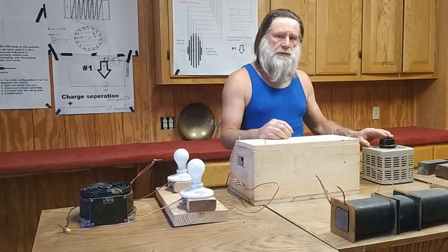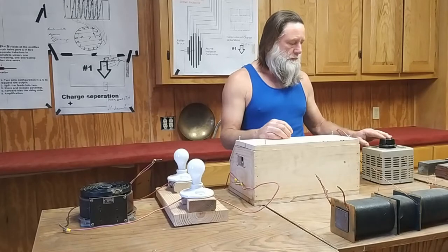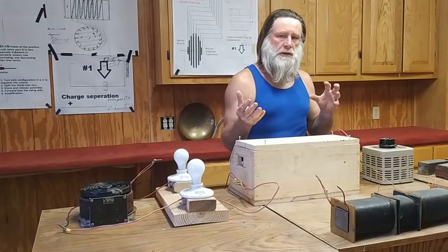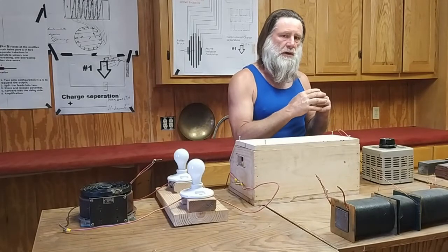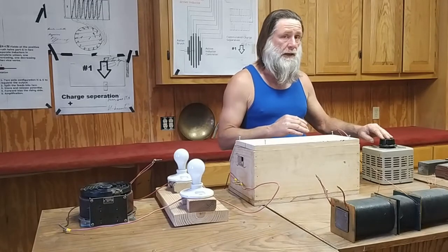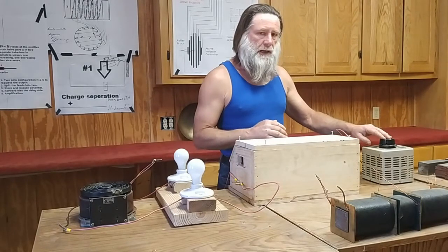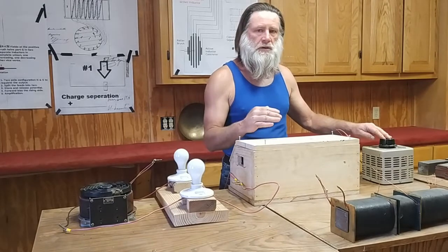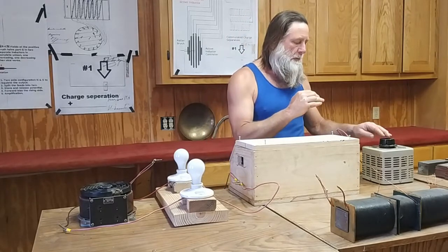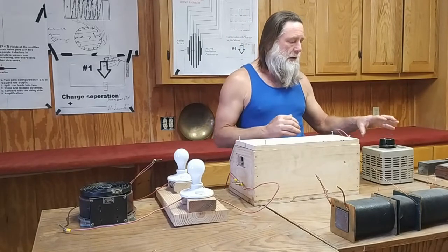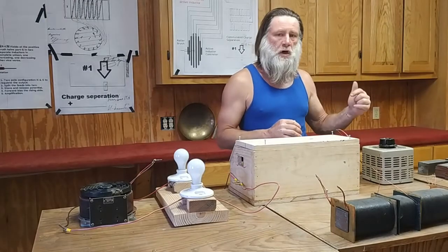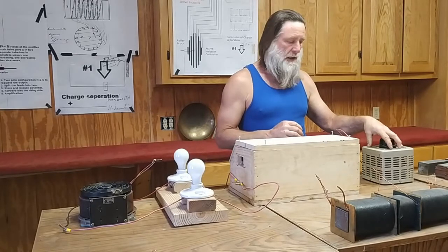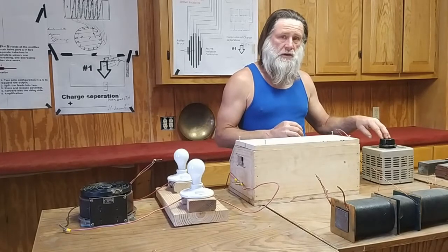Now, when you have current flowing through here and they magnetically link, according to Lenz's law, it will oppose the original current flow. But because you have AC, alternating current, it's not the fact that it travels in two different directions. That's totally inconsequential. The method behind the madness is that it's the constant rise and fall that causes the inductive reactance and makes the Variac work.